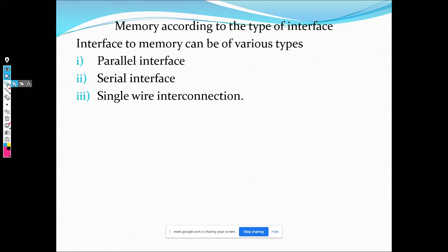It's going to look like this, right? You have multiple wires connected together, and then you have the connecting port here. So that's your parallel interface. Every single line here corresponds to one bit of your signal. So it's a multi-bit wide signal you want to transfer. You transfer the bits parallelly, in 8 bits or 16 bits, like that.